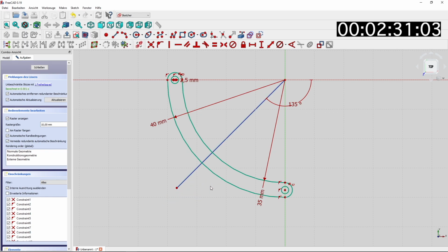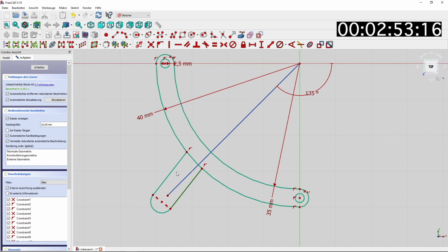One last thing, we need to add the notch, and this is done with the polyline. Just go here, letter M to switch the behavior of the polyline, and go here. Glue this one on the outer arc. Pretty simple. Select these two, make them parallel, and now make them also parallel to the 45-degree here in the middle.